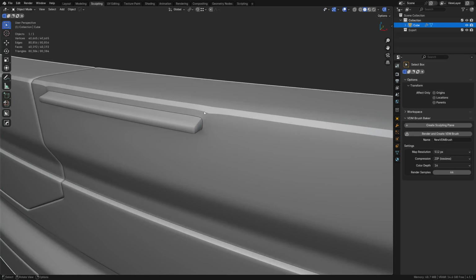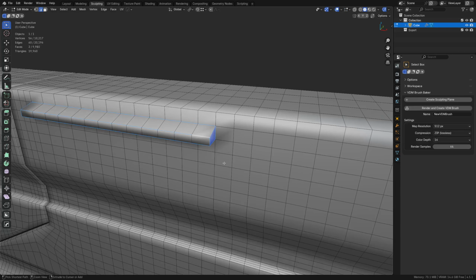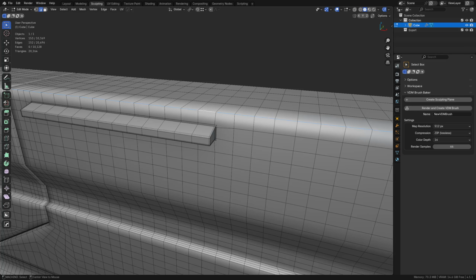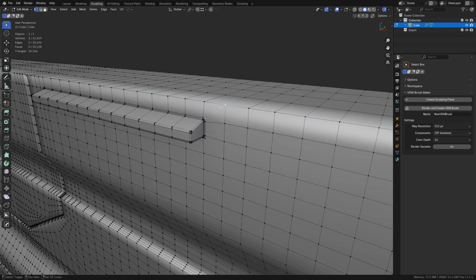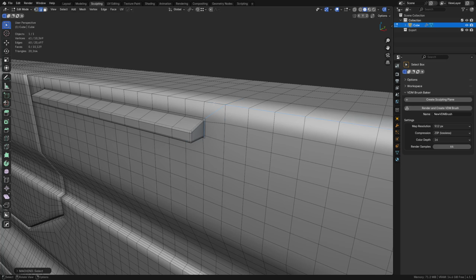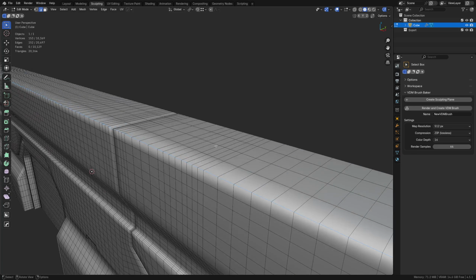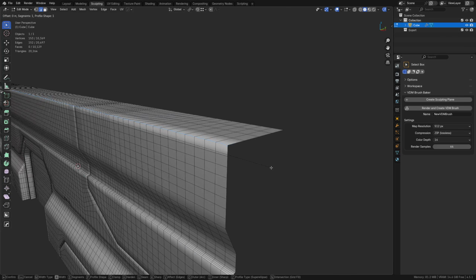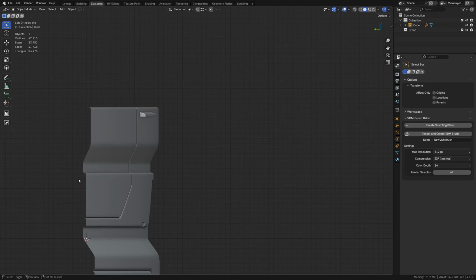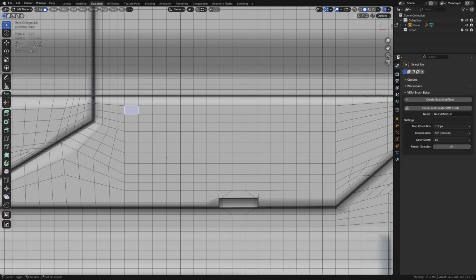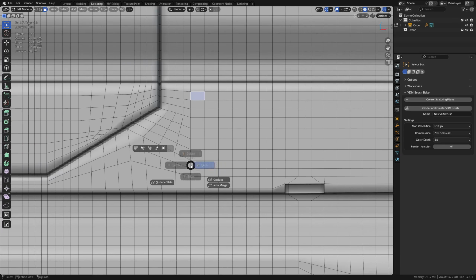Now you notice because we're doing just regular subdivision at this point, we have a little bit of an issue with that corner there. Okay, because that whole top edge is getting pulled, because basically this is turning into something like this, which is what you want anyways, but we kind of want to get through that whole top edge at some point. And we can kind of reconfirm this edge if we want by just doing a little bevel on it. That's a little bit smaller. So you can start to control all the fine detail of the model now. You can make little panels, and you can still do lots of cuts and all kinds of fun stuff, but you'll have to fix the topology around it.